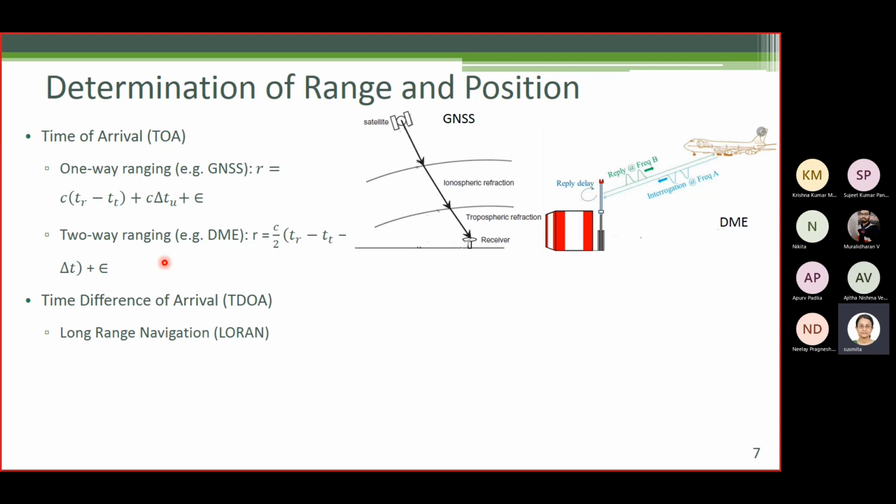Now, how can the user identify a chain? Each chain has a unique repetition interval, the group repetition interval. This is the interval at which the group transmission repeats. In other words, it is the time between two successive master transmissions. First the master transmits, then all the secondary transmitters transmit one at a time. Once all the secondary transmitters have transmitted, the master transmits again.